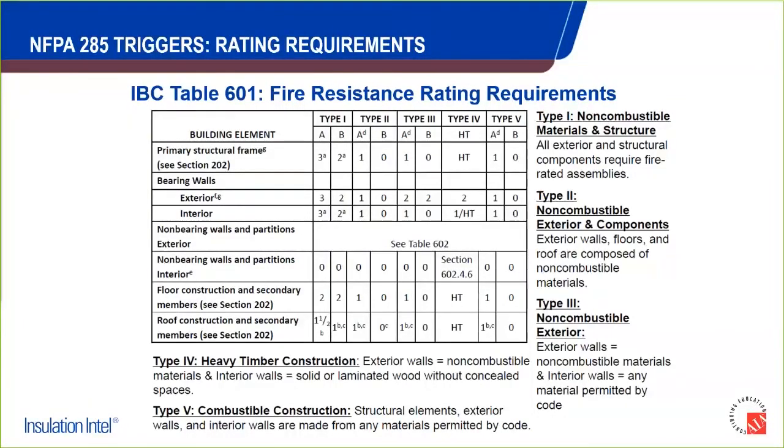And what types of buildings is it required for? So getting into sort of the nitty-gritty of the triggers for NFPA 285, it's really only for technically non-combustible buildings.